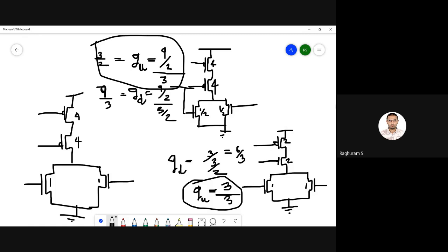We can, if there are some special cases where one particular transition is better, then we can improve the performance of the gate for that transition. The other transition has become worse, but we don't care because that transition happens very rarely, or that transition has more time to perform the operation, etc.